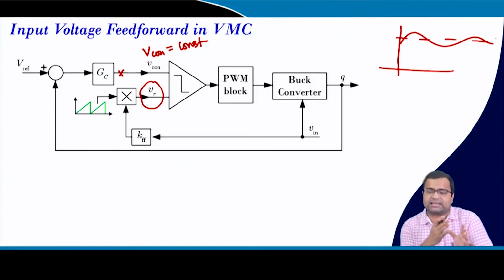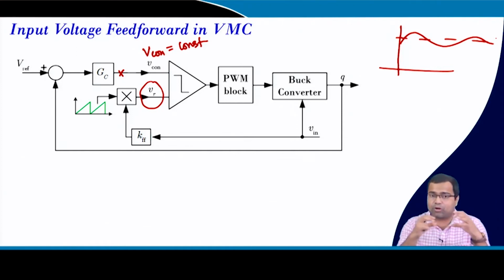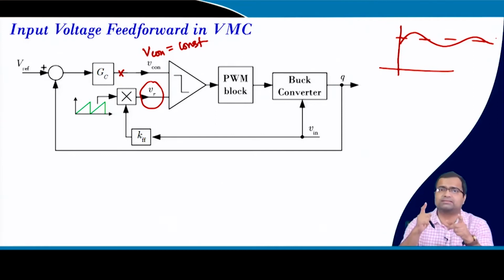And in the previous lecture, lecture number 13, we discussed if you consider a practical voltage source, which has some impedance, or if you poorly connect the wire cable of your power converter, and the supply is not very well regulated, then this output impedance of the supply, which may include the cable resistance also, can drastically change the behavior of the source voltage across the buck converter when it is driving it, because your buck converter has a pulsating or discontinuous input current.